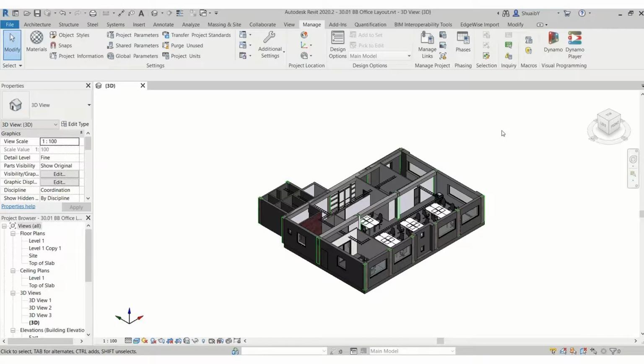Okay, so just to summarize what we did in Civil 3D, we set the location so that it's under the correct coordinate system. Then we went to the toolbox, we went to under subscription extensions, and then we right-clicked on shared reference point and hit execute. And then we selected our coordinate point, which was given. And then we selected another reference point on that building footprint to allow the rotation of the building. So now I'm going to show you how it looks in Revit.